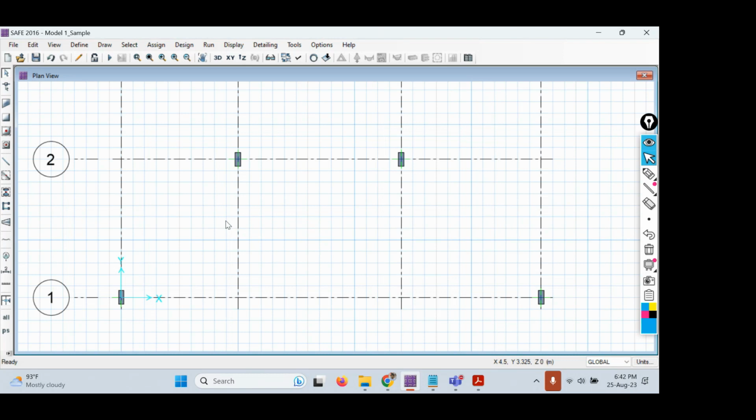Right. Now, one thing that we have to remember here is don't select the column points by keeping in XY plane. The reason is if you select the column points in the XY plane, there will be some errors. Why is that? Because for every line, if you consider this line, let me make it bigger. If you consider a column, for every column we have 2 points. One is at the top and another is at the bottom.